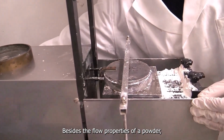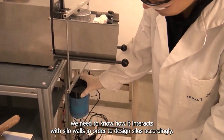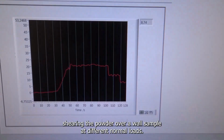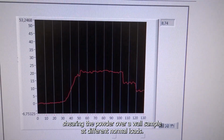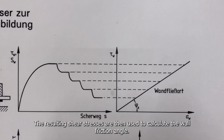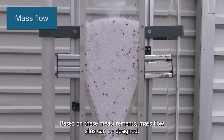Besides the flow properties of a powder, we need to know how it interacts with silo walls in order to design silos accordingly. The interaction is measured by shearing the powder over a wall sample at different normal loads. The resulting shear stresses are then used to calculate the wall friction. Based on these measurements, mass flow silos can be designed.